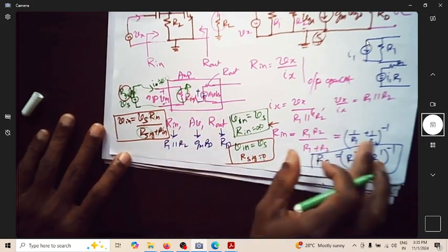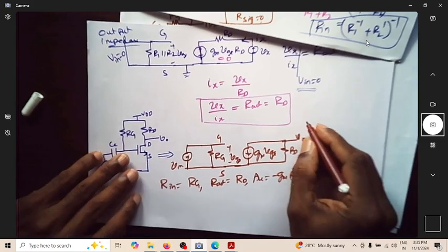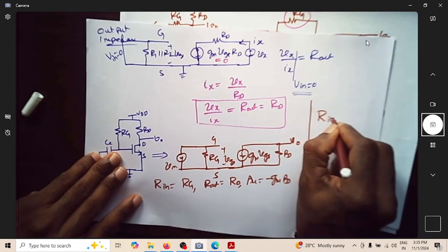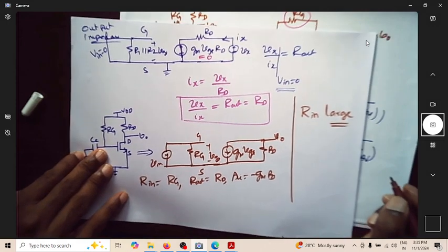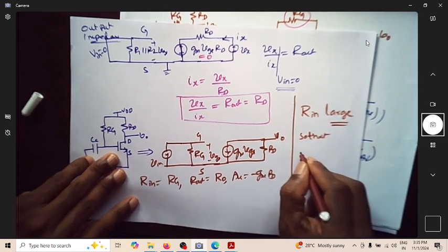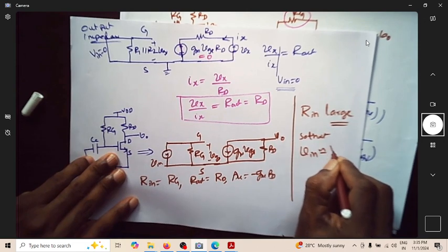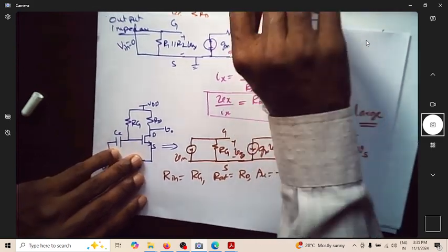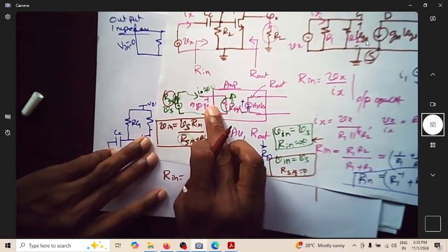So for a typical case, you should have input impedance very large, so that the input voltage of the amplifier is approximately equal to the source signal that is being used here. So the entire thing will reach here. That's what input impedance is.